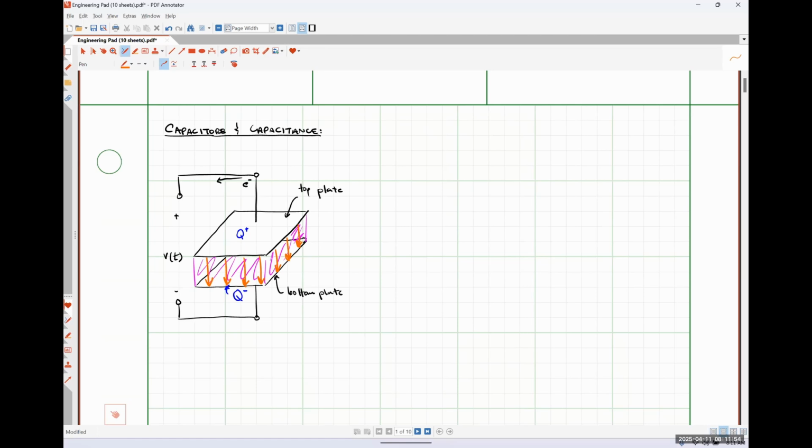So these are the basics of how capacitors work, okay? We essentially store energy on the plates in the form of charge and introducing that electric field. And then as soon as we change that voltage, some amount of charge is going to be released back into the system, okay? So from that relationship, we could say that the current that's flowing through our capacitor, IC of t, is going to be equal to the derivative of the charge stored by the capacitor.